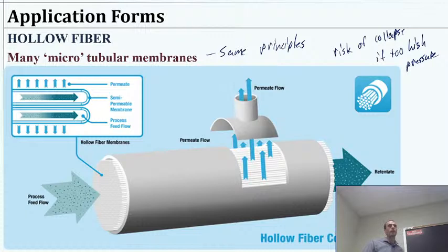Now we've got something in here that's just really too large for this to handle, and it physically scratches the membrane. Now you have a leaking membrane, one of the fibers or a couple of the fibers, and so that kind of compromises the entire membrane unit here.